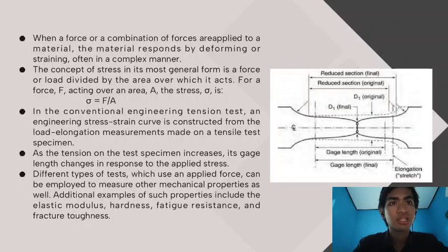While the material is under load, the resulting change in cross-sectional area depends on the material property and the magnitude of the applied stress. True stress is based on the instantaneous cross-sectional area under load, and is therefore a more accurate method for characterizing the stress.